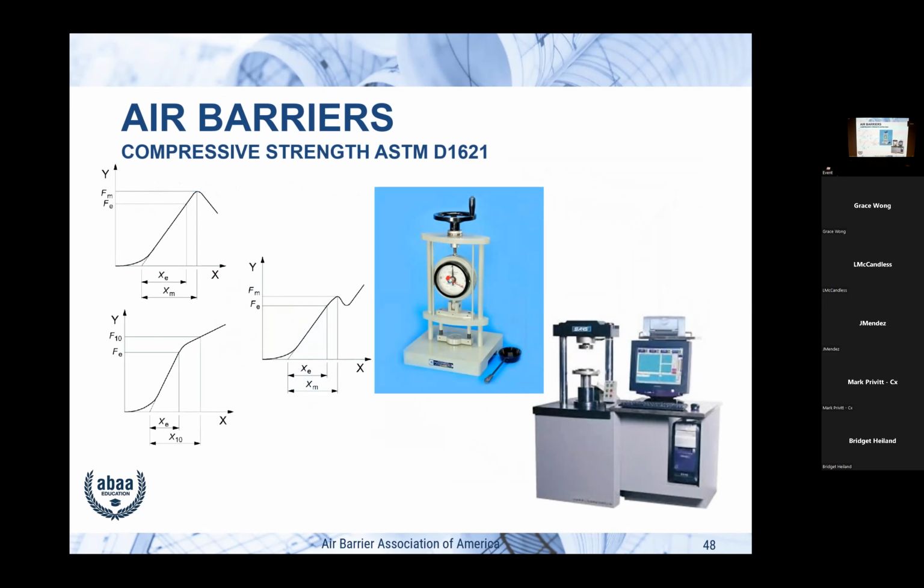After dimensional stability, the most important one is your compressive. If you have the right compressive, which is generally around 40 psi for medium dense, then you know all your other material properties are going to be good. Your water vapor transmission rate, your heat flow, everything else, because you know you got the right material there.